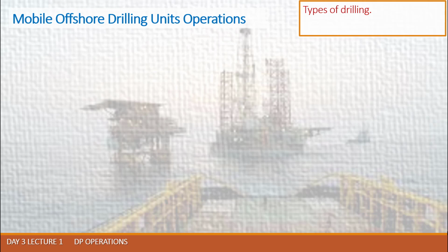When I say 3 or 7 degrees, I mean that at a deep water location, 3 degrees deviation of the riser from the BOP position will give you a normal operational sector at the top of the water surface. But 7 degrees deviation of the riser from the BOP position will give you already a critical situation.